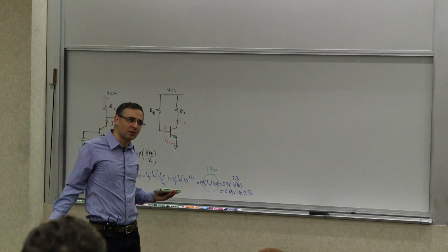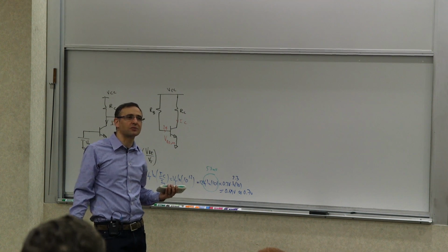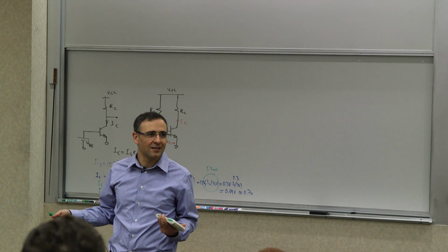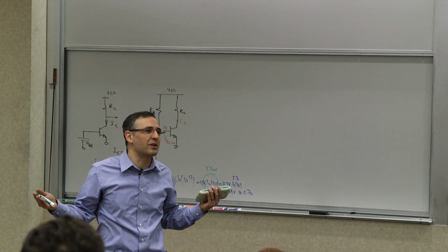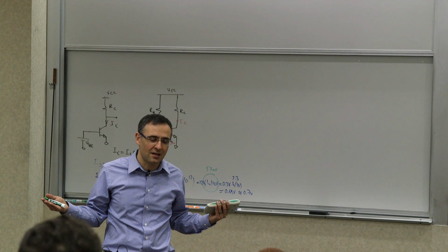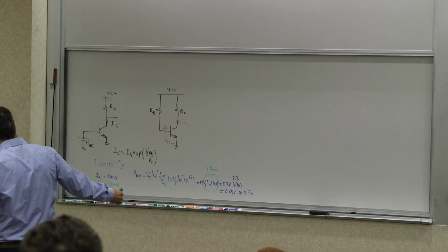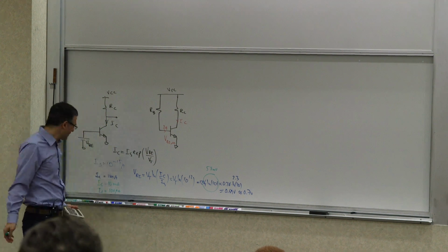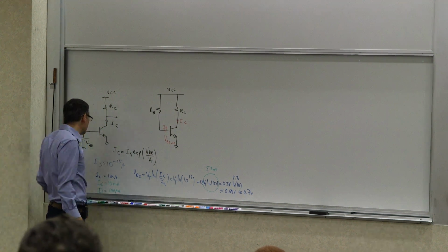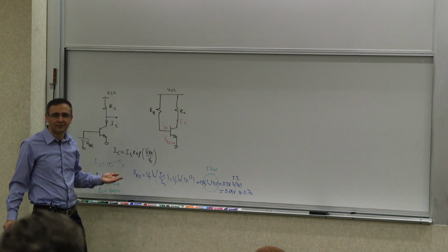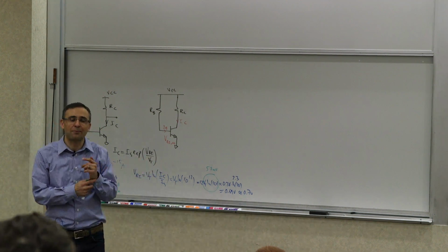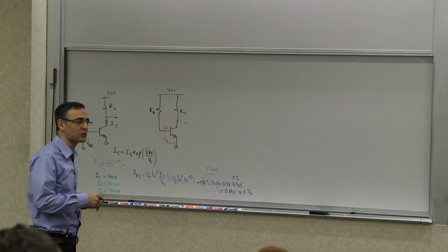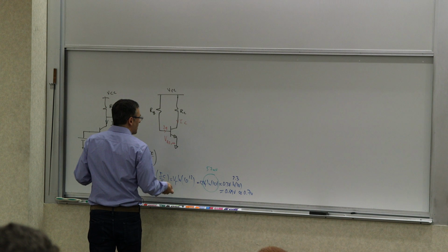So as long as I'm within a couple orders of magnitude of that, I'm within 60 millivolts, 100 millivolts of that. So that voltage is going to be in the range of 0.6 to 0.8 for typical currents. Now, if you're operating at like 1 nanoamp, then that voltage is going to be very different. Right? So there's nothing magical about that. It's an artifact of the value of IS you get, which also has relationship to band gap of the semiconductor and things of that sort, as we'll see later when we talk about temperature-independent biasing. But that's what it is, right?